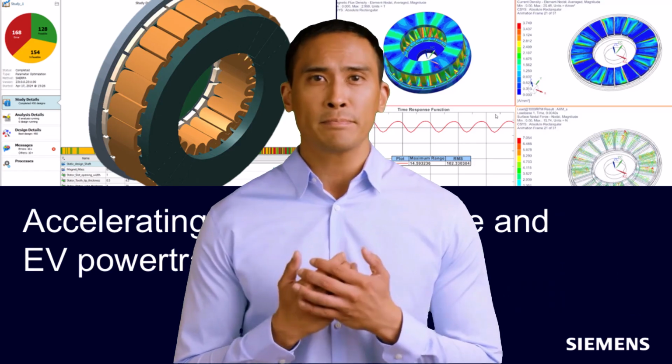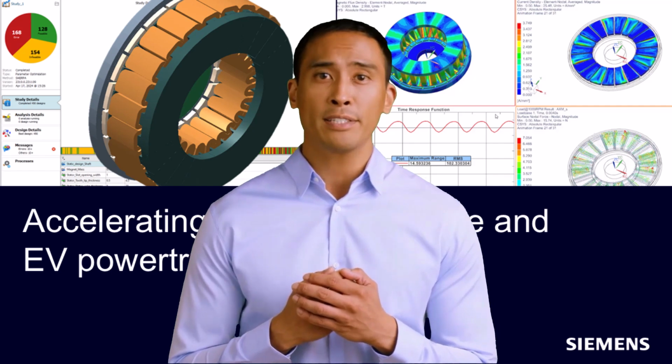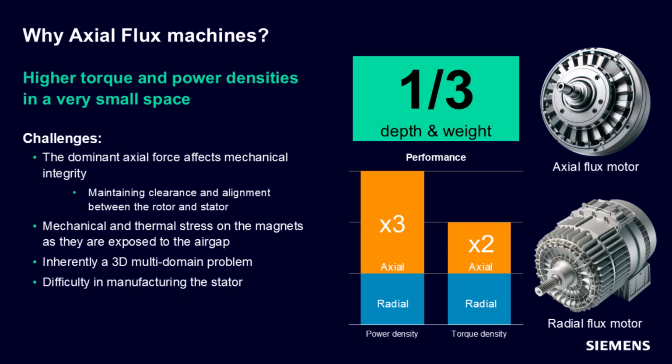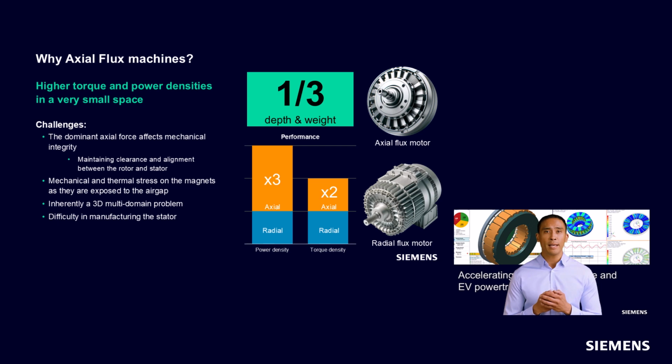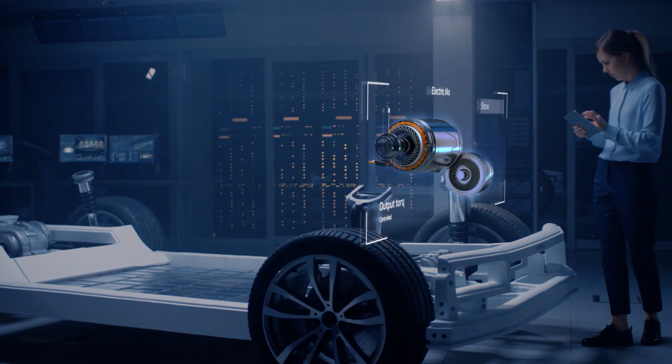But axial flux motors pose engineering challenges too, such as the need to reduce electromagnetically induced noise and vibrations, manage mechanical stress on the magnets, maintaining a uniform air gap and mechanical alignment, and the need for thermal management. However, current simulation workflows require weeks to simulate these kinds of conditions for axial flux motors.